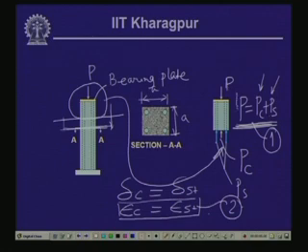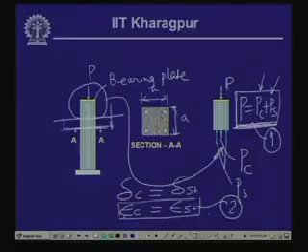So, this condition, that P is equal to PC plus PS, is termed the equilibrium equation, and another equation in terms of forces, generated from the second equation, where strain in concrete is equal to strain in steel, we call the compatibility equation.